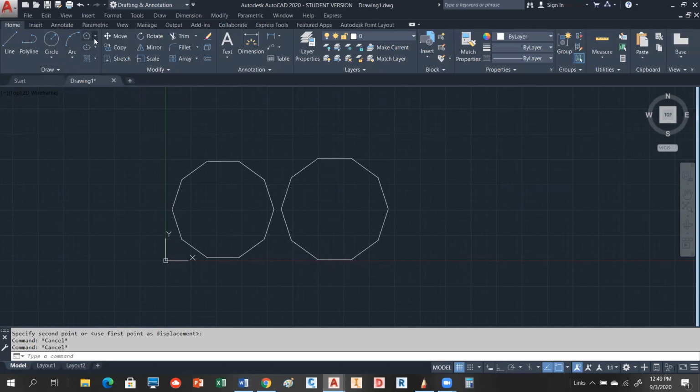So we're going to go here, and we're going to choose polygon. Let's knock this down to a three-sided figure. So we're going to say 3 sides this time. And instead of choosing the center point option, I actually want to choose edge. Okay. So it wants me to pick a starting point for my edge. So I'm just going to pick that right here.